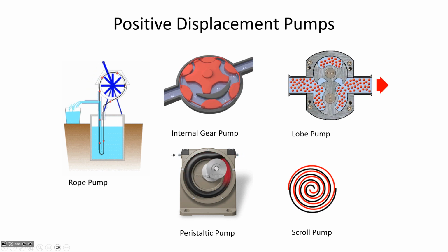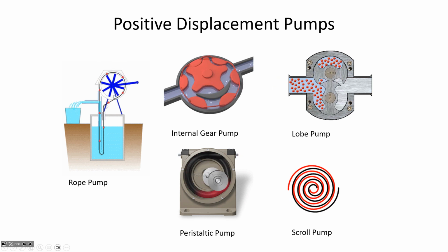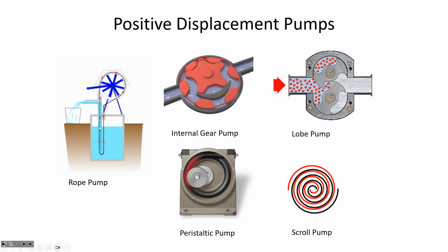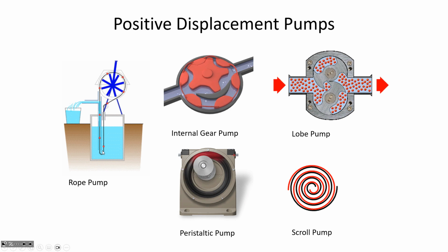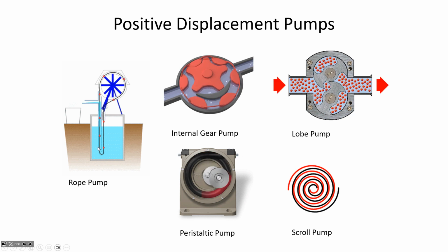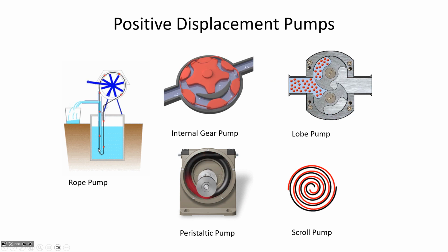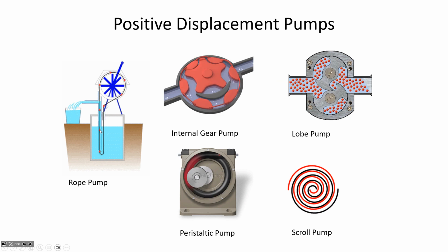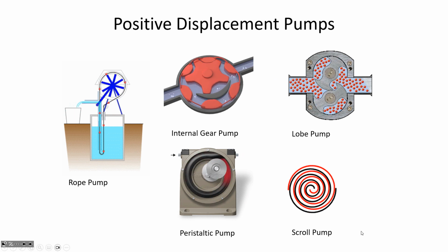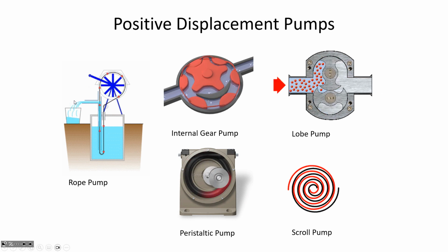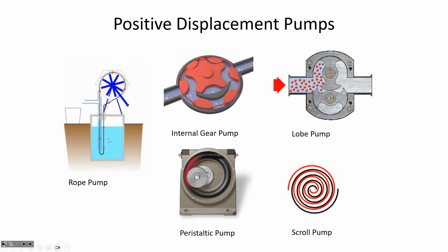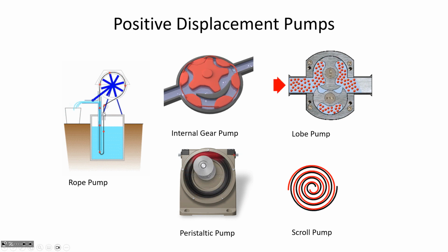It could be a groundwater reservoir, or water at a lower water surface elevation like in a lake or a creek. With each crank of this handle, which is connected to the rope, it's drawing the plug up through a pipe. The rubber plug has a diameter that's just barely smaller than this confining pipe that's also down in the water. So the plug is sealed, it's lifted up, and the water is perched on top of the plug, and then there's this outlet pipe where the water is discharged out to a bucket. So with a rope pump, each cycle is drawing a certain volume upward.